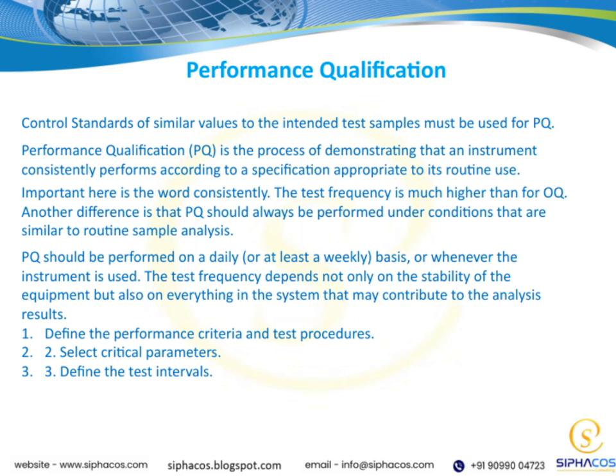Also, it's crucial that PQ is performed under conditions similar to those during actual sample analysis. This way, we're testing in a realistic environment, making our results more applicable to everyday use. In terms of timing, PQ should ideally be done daily or at least weekly, or every time the instrument is used. The frequency depends not only on how stable the equipment is, but also on any other factors in the system that could influence analysis results.